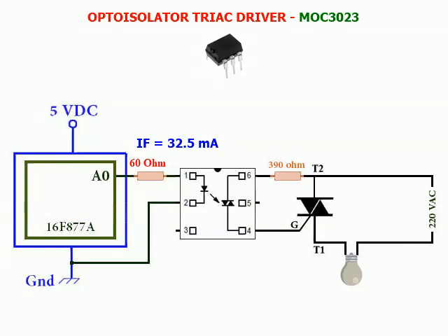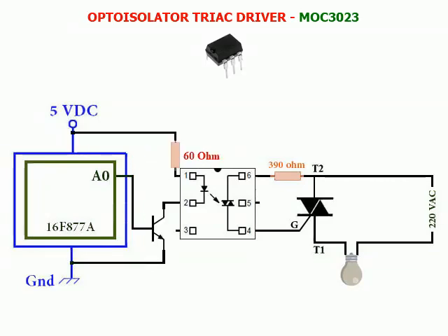But it is always better to avoid drawing high electric current from the microcontroller, so it's recommended to power the LED using a transistor. Now, instead of drawing 32.5 mA from the microcontroller, the transistor just needs a few microamperes on its base, to get connected and turn on the LED, which draws its current from the main power supply. This is a good improvement over the triggering circuit, however it is not necessary.